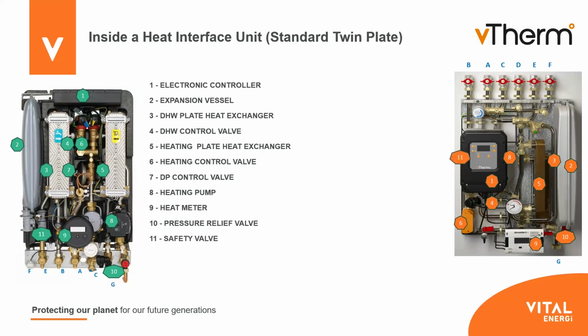We have a safety valve. So the safety valve is an electronic or mechanical spring returning to tight shut-off valve. And this is used if you think of, let's say you're having a shower and suddenly power is lost to the HIU, the controlling valves suddenly stop where they are. You could therefore cause a scalding issue. So the safety valve actually shuts the primary circuit down, and therefore, worst case scenario, you get a cold shower.